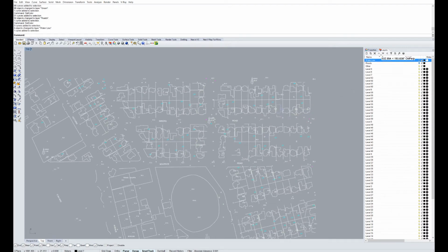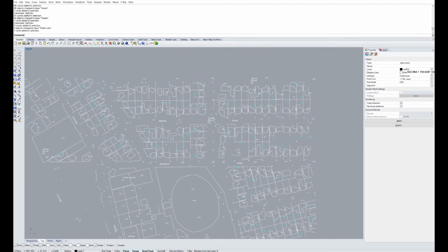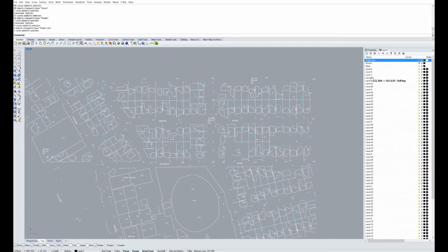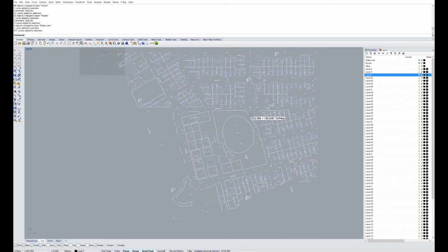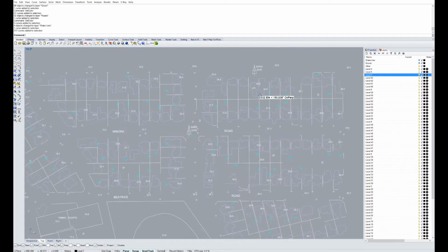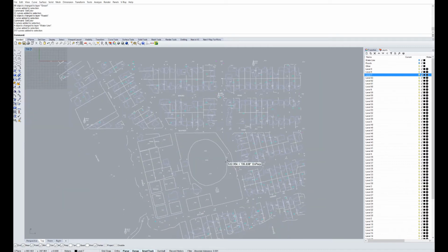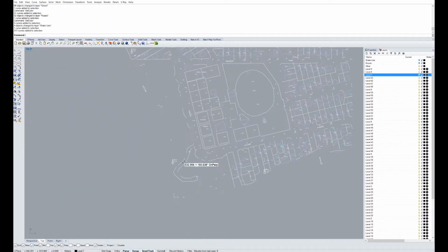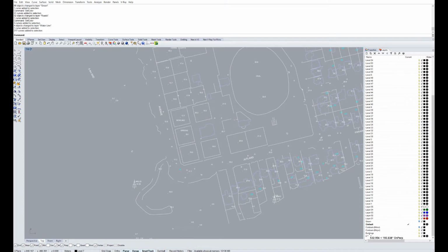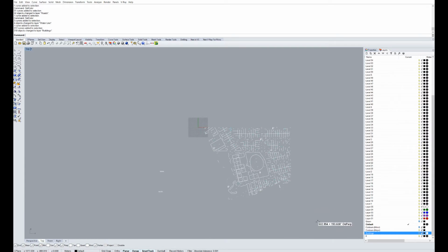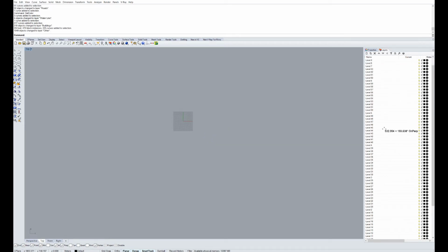Now hopefully the buildings, I'm not sure which layer they're on, level 7. Let's have a look, level 7, select objects. Okay, it looks like these are buildings, because they kind of mix together with text, parcels, and fences and things. And looks like retaining walls as well. So I'm just going to go ahead and put it on the building layer. I'll just hide that, and maybe put everything else on the other layer. So now I actually can tell where my objects are just based on these names.